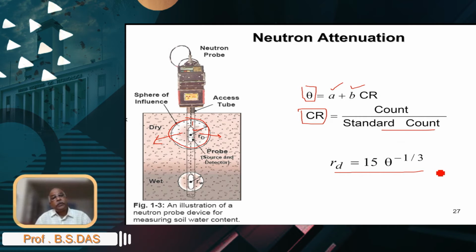So with a very wet soil, typically your volume of measurement is small. You are measuring water content in a smaller volume, whereas in a dry soil you are measuring in a larger volume, and that really gives you uncertainty about where you really measured water. And that's one part of it.